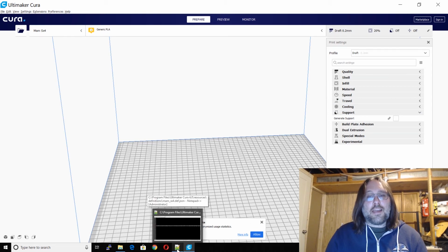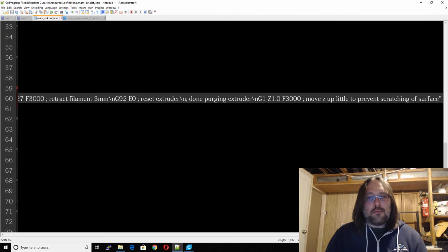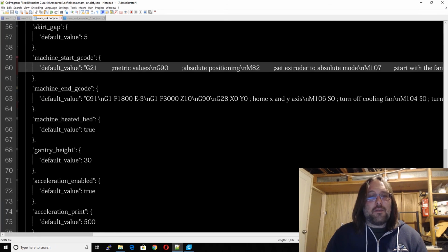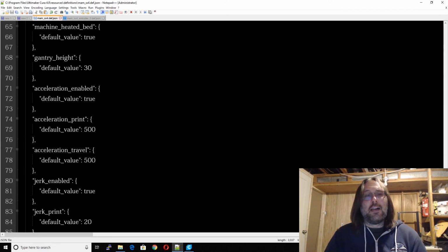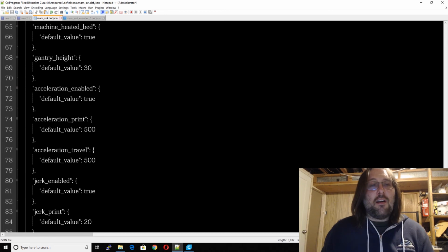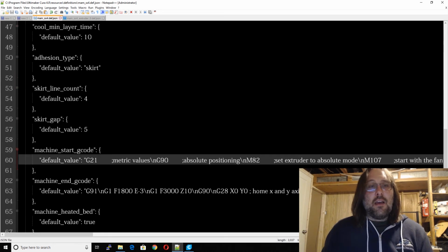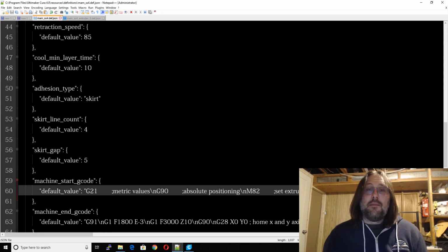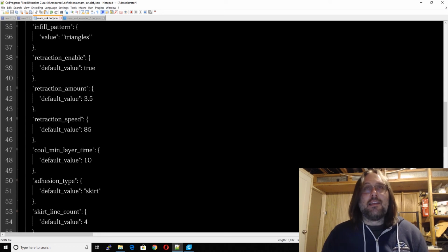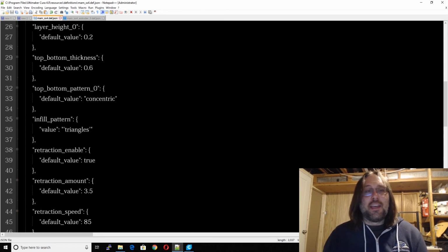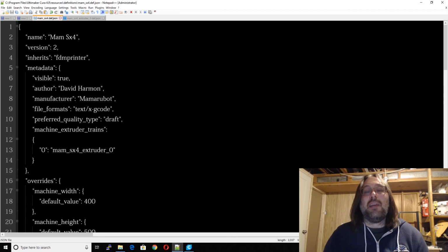So coming back to here now, don't be afraid if you need to edit the other values in the file. JSON is an instruction file for Cura that just has settings in it. So you can come and change all of your values in here if you need to. It's open source. There's a GitHub, and I'll post the link in the video description here. The GitHub actually has printers that people have made and Cura has approved, or Ultimaker, I should say. So you can luck out sometimes and find your printer in that list.